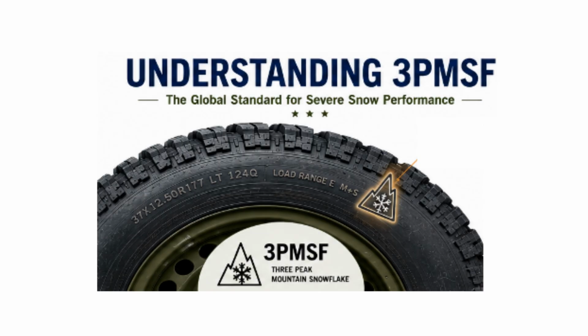However, the marking should not be misunderstood as a guarantee of maximum grip in every winter situation. It does not automatically confirm equal performance on ice, deep snow, wet roads, or during braking and cornering. Engineers should therefore consider 3PMSF together with tread design, rubber compound, load rating, inflation pressure, temperature range, terrain, and vehicle requirements. In simple terms, M+S is mainly a tread classification, while 3PMSF represents tested severe snow capability.